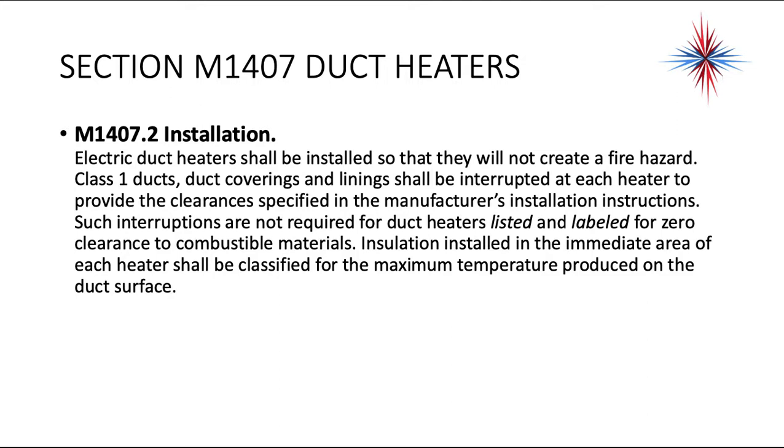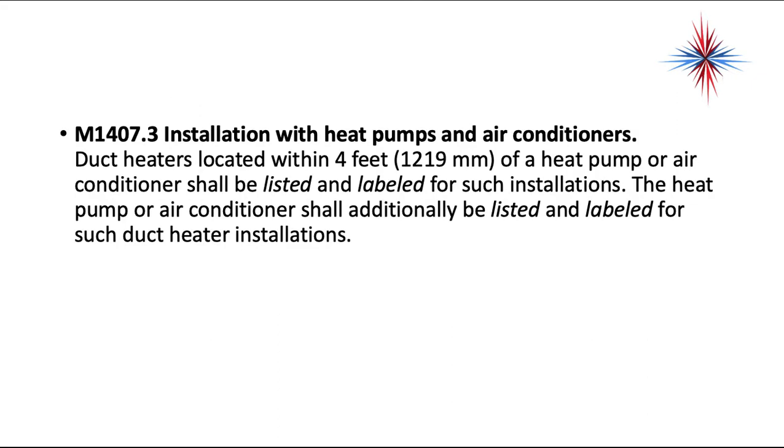Electric duct heaters, including heaters that are on top of air handlers, need to be protected from insulation in the ductwork catching on fire. Installation with heat pumps and air conditioners: a duct heater located within 4 feet of a heat pump or air conditioner shall be listed and labeled for such installations. The heat pump or air conditioner shall additionally be listed and labeled for duct heater installations.